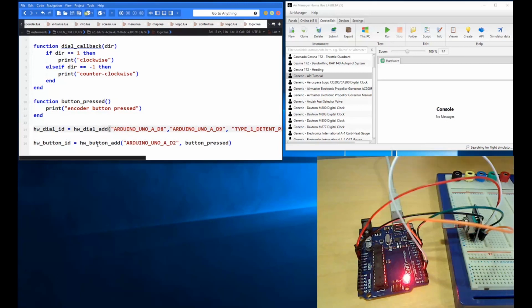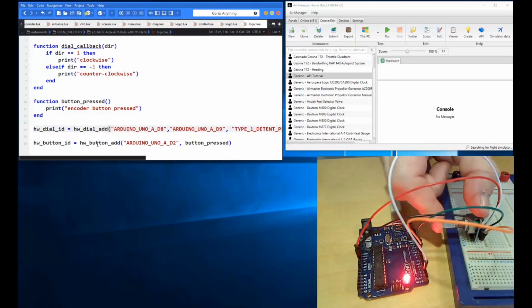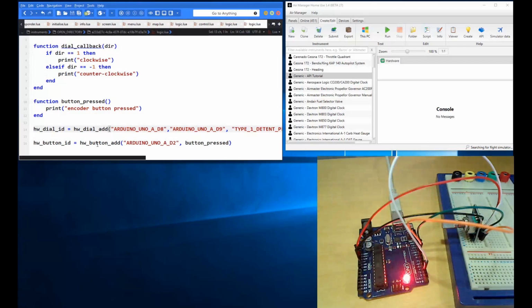Because this particular encoder, as do a lot of encoders, has got a button. You push the shaft in and you get a little click button on the encoder there. So sometimes you find that the encoder button has got an action associated with it. Even though it's not related directly to the encoder, because we've done button already, it's just to show you how that comes out on a separate pin of the encoder if they have a push button, and you treat it just like a normal button.